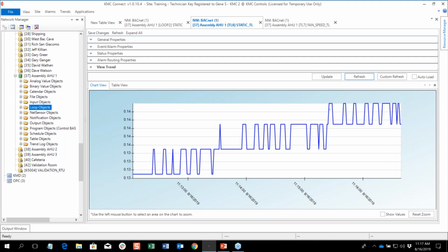So the other couple questions we got relate to pausing a PID. A PID, again, it responds because the system is ever changing. The calculation is always dependent on what's happening in the system now and the error that it's seen since it's been running. If I wanted to change what gets plumbed to the output and pause the loop, my preference would be to do that in Control Basic.